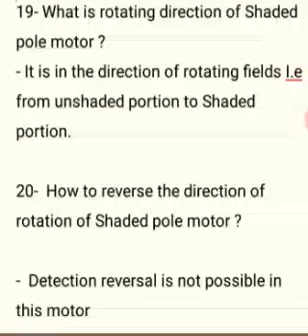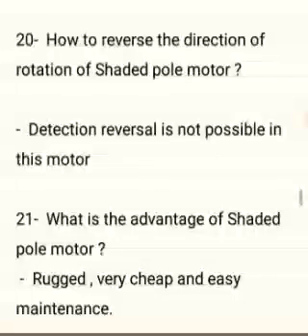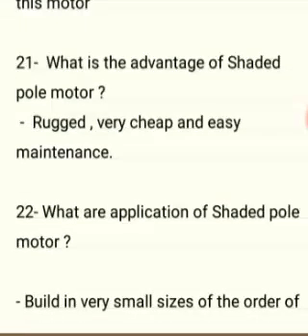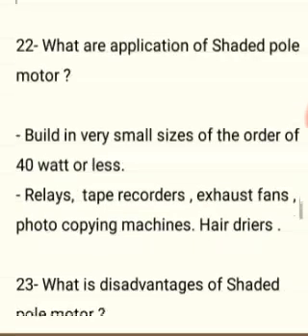What is the rotating direction of a shaded pole motor? It is in the direction of the rotating field, that is from the unshaded portion to the shaded portion. How to reverse the direction of rotation of a shaded pole motor? Direction reversal is not possible in this motor. What is the advantage of a shaded pole motor? Rugged, very cheap and easy maintenance. What are the applications of a shaded pole motor?